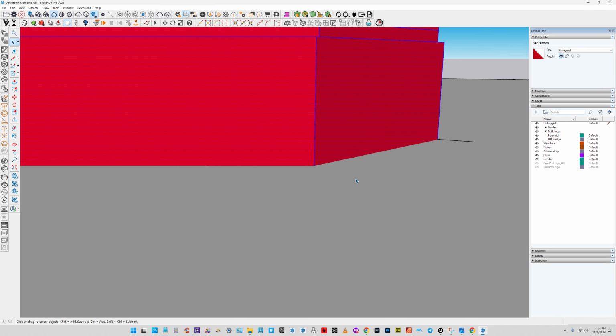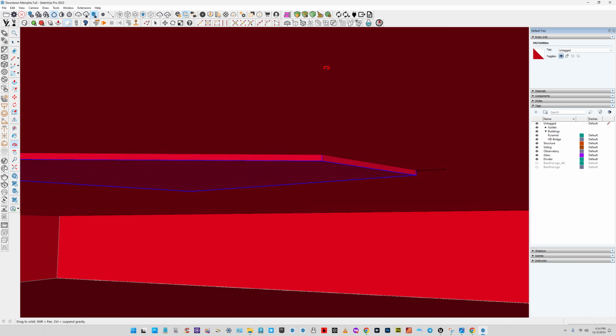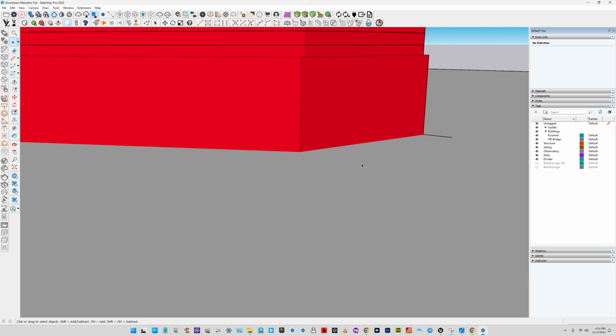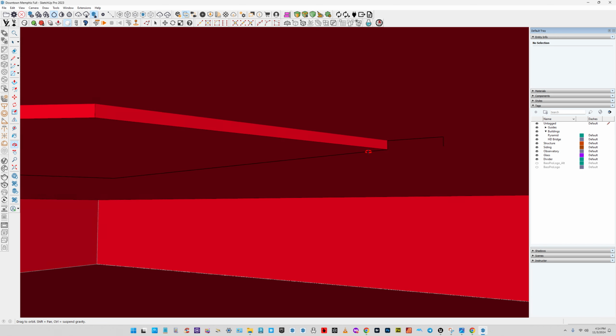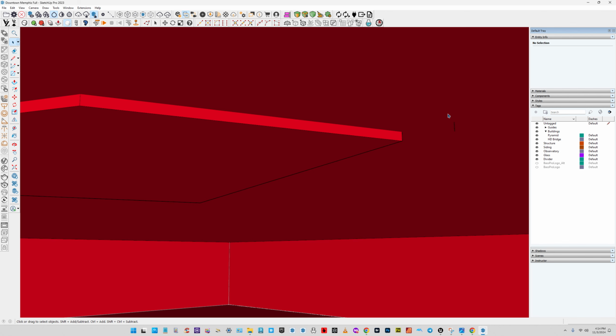Clean that model up. I use the clean tool, which is something you can download at the SketchUp extensions warehouse, to clean all those extra lines off of these rectangles. And now I'm going to push-pull this up to the floor. Actually, no. I need to draw a line down to here so I can figure out how far underneath my 0 point this building, this floor, sinks into the ground.